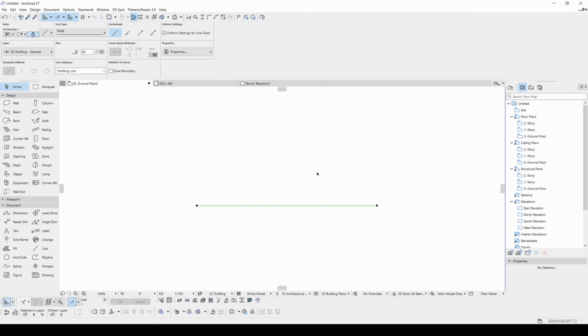These 2 different points determine your line position and direction. You can customize it by clicking your points directly, like this. And if you click your point, a new menu will appear like this, and it's now on the stretch command. You can change this to multiply, mirror, rotate, and drag.